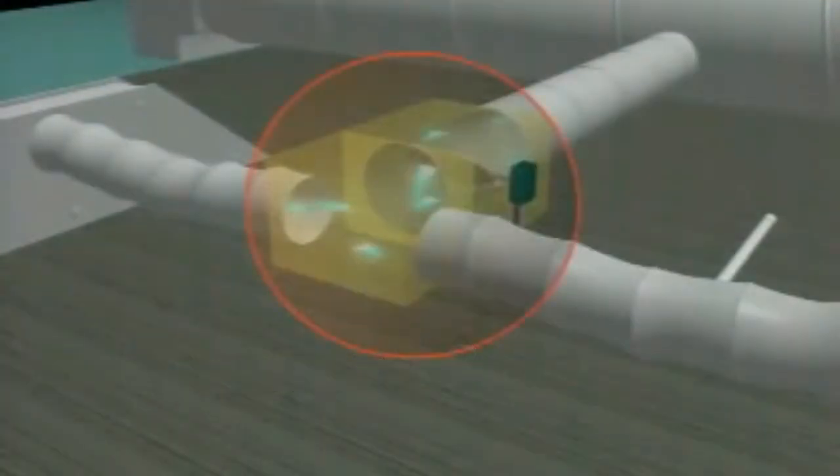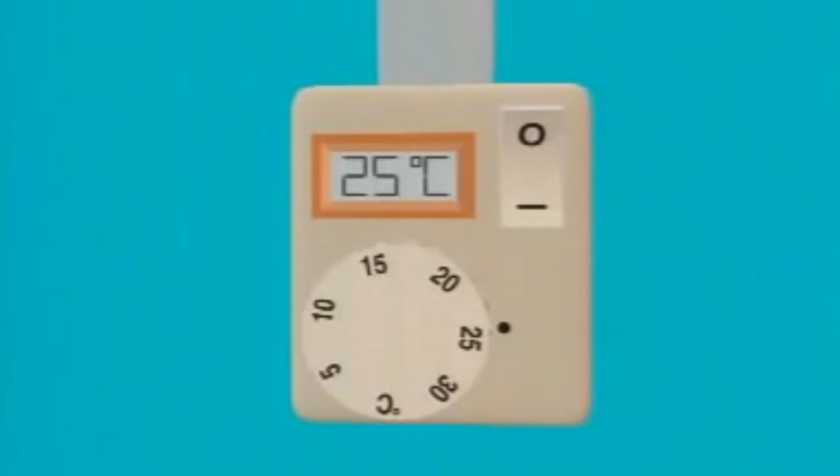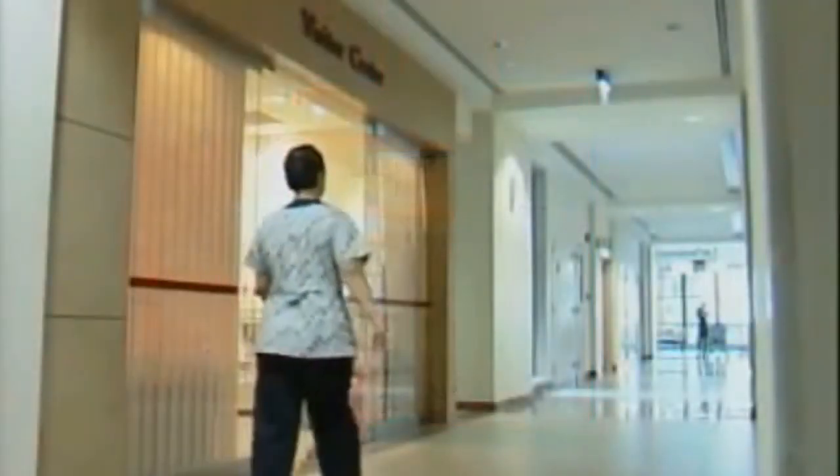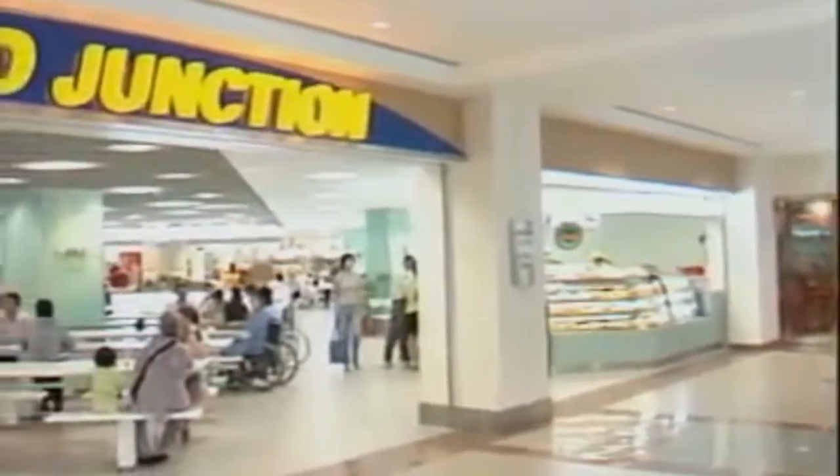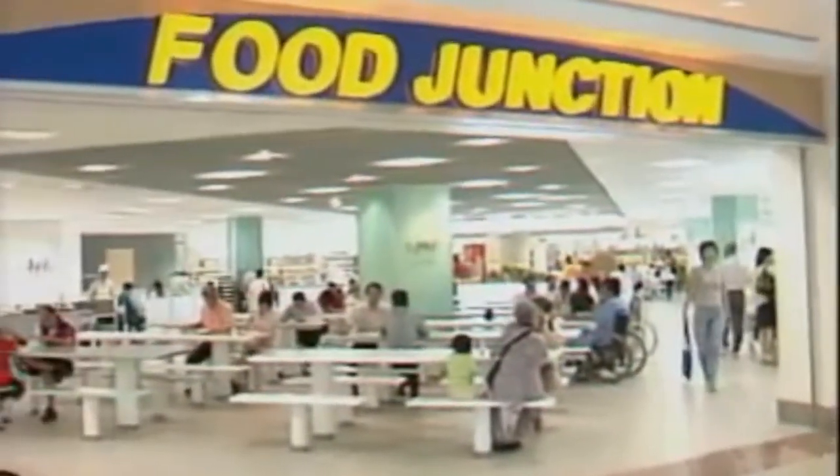The damper inside the VAV terminal box is therefore activated to rotate to provide a larger opening position to increase the supply air volume flow rate. As a result of more supply air, the temperature of the room is returned to its set point temperature. If the temperature of the room drops, the damper plate will rotate to close, thereby reducing the supply air volume flow rate.